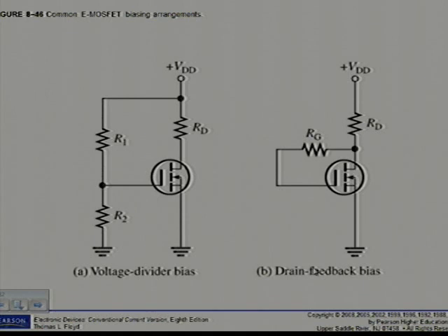Alright, on page 405, E-MOSFET bias. Because E-MOSFETs must have a VGS greater than the threshold value, if you can recall the characteristic curve that we've just looked at, zero bias, of course, cannot be used. Underline that. Makes sense, no? If we remember the characteristic curve.